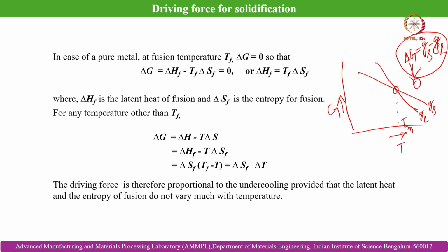So here this is the equilibrium state of matter, and if we increase the temperature further, it will be prone to go towards the liquid state, because the free energy of liquid is lesser. But that is not the case when we go below the equilibrium melting temperature. In that case we will see the free energy of solid is lesser than the free energy of liquid. That is why there will be a transformation from liquid to solid state as we fall below the equilibrium melting temperature.